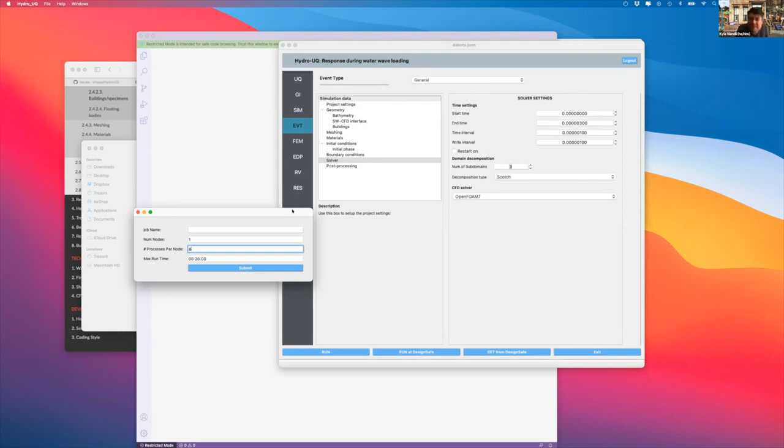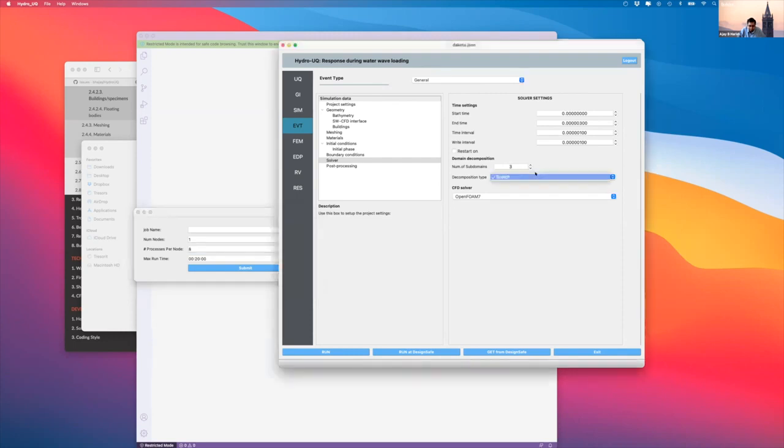Right. So the two things that we have done here. One is that the Scotch method that OpenFOAM uses does some load balancing automatically. When it's dividing these domains, it tries to ensure that the number of faces intersecting between the domains is as small as possible. Because if you have a common face between two domains, then that's a common cell and a common face center for which it needs to do communication. So firstly, it tries to minimize that. Some load balancing is already taken care of in there.